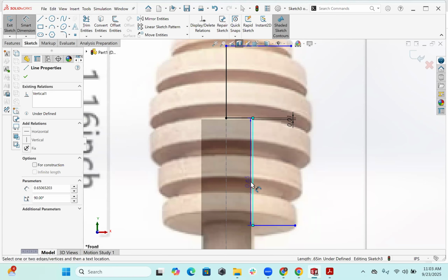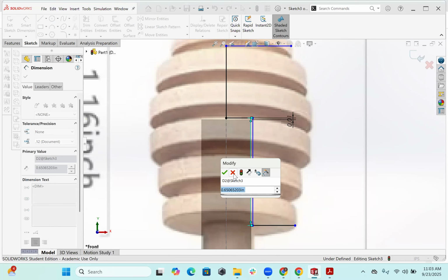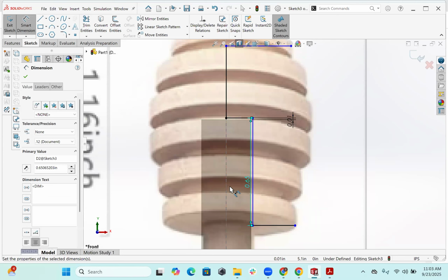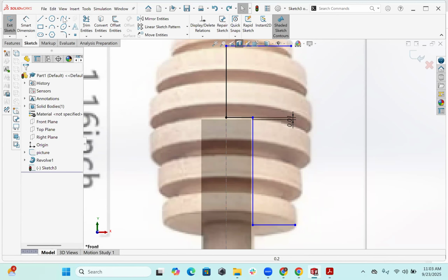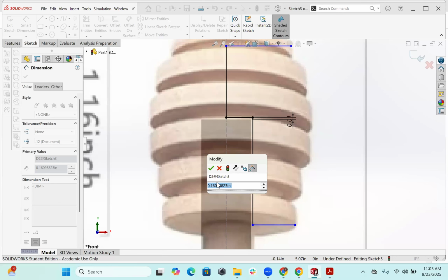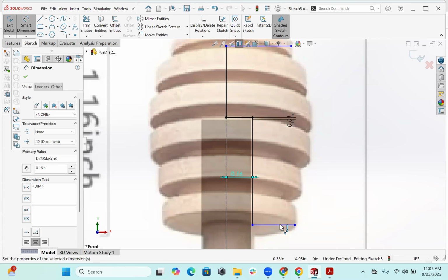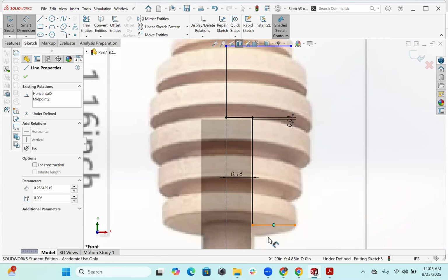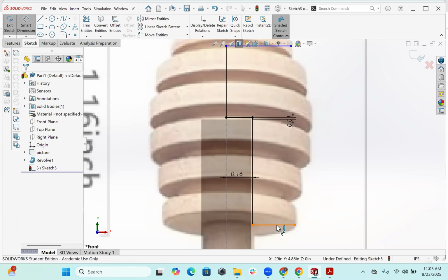And from here, it did not do that. One thing we could do is now measure from the center, from here to here. It was a 0.15, remember? So now we do 0.16. So that gives us that 0.1 spacing. It is very common if you go in the center and you pick that dot, it doesn't measure anything. For example, here. It happens. So you just have to press escape to deselect that dot.